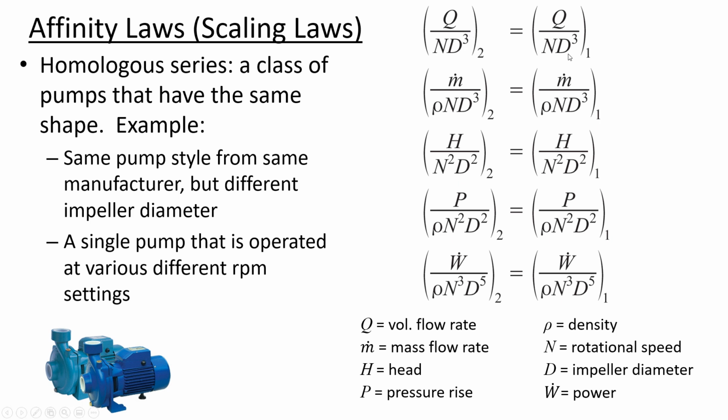The diameter variable there is just in case there were related pumps and they had similar shape and those same kind of characteristics, but we wanted to know how the known behavior of one of the smaller pumps is being used to predict a larger pump. And so the main thing to keep in mind from this first equation is it's used to predict the ratio of flow rates. And so the 1 and the 2 are just referring to pump number 1 and pump number 2.